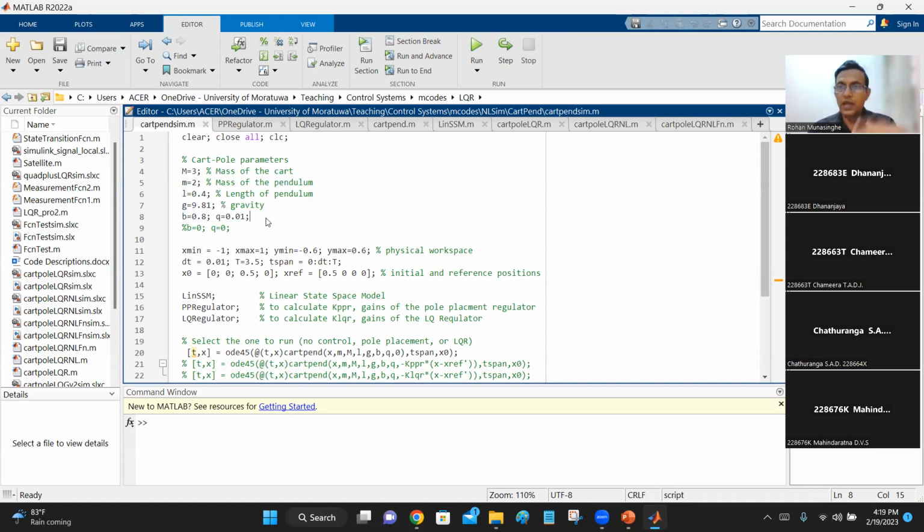Without that, the system will not be stable because you need friction to take the energy out so that motions are gradually diminishing and system converges, right? Do not simulate ideal things without any friction and all that, because you will easily make the system unstable. Always have some sort of damping in the system to take the energy out so that you can see something very realistic on your screen.